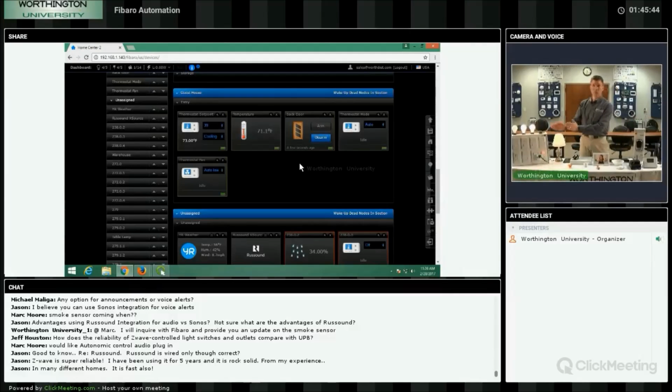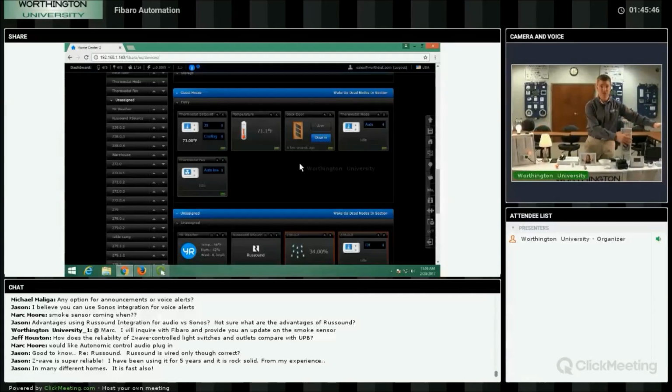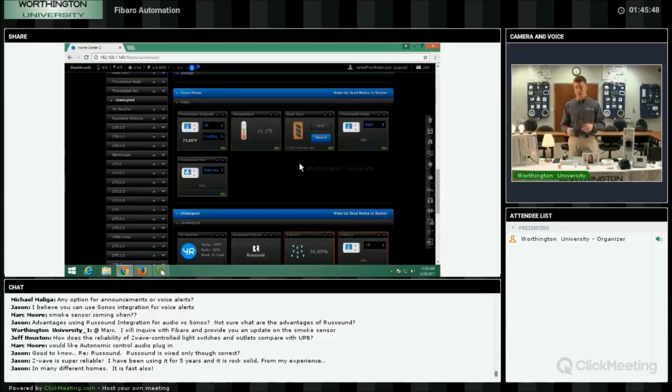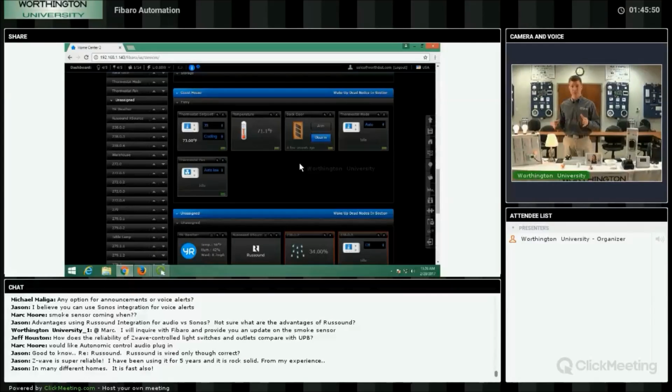So what I have is from here over is one Z-Wave network, and from here over is a separate Z-Wave network, but they're working together as one. So not only do we have really super good reliability within its own network, if we get too big, if you come to us and say, I think I threw the number out, 10,000 square foot house, I would not recommend you doing that with one Z-Wave network. They're probably going to be too spread out.